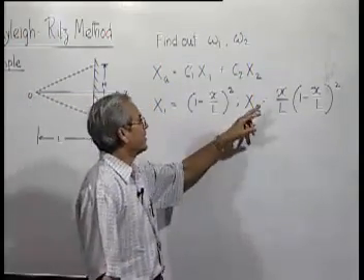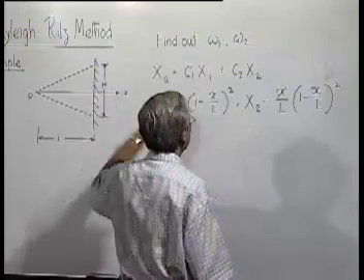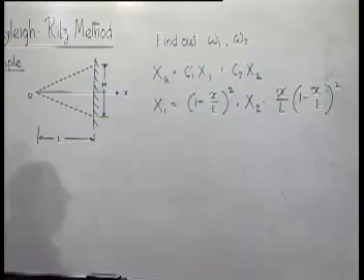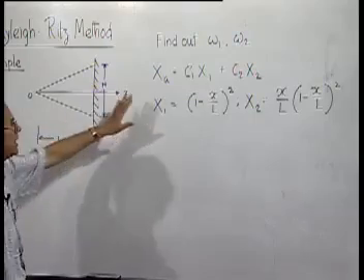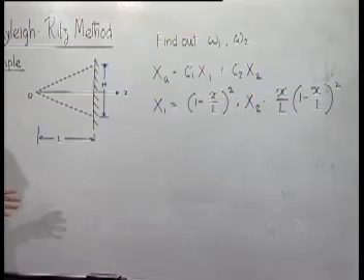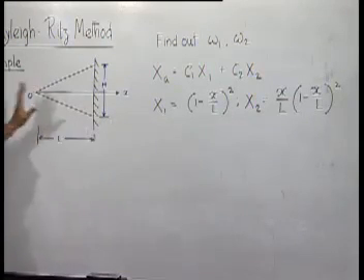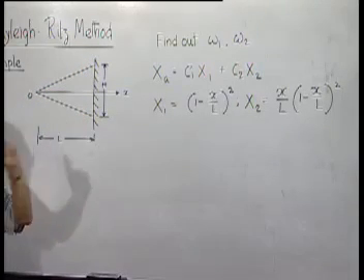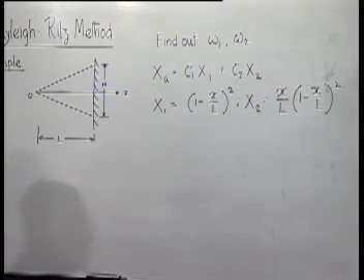But at the other end, if you see, at x equal to L, it is satisfying, both the slope and the value of deflection are 0. So therefore, X1 is satisfying the geometric conditions, X2 also is satisfying the geometric conditions at this end, but neither X1 nor X2 will satisfy all conditions. Anyhow, our objective was whether it satisfies the two conditions here or not. So we have kept that in mind. Only two conditions are being asked to be satisfied.